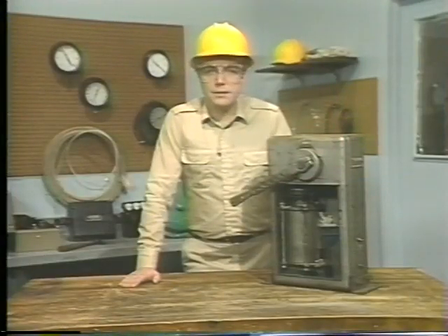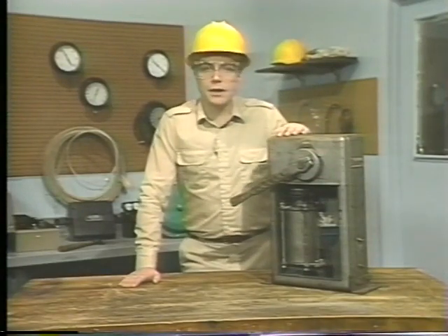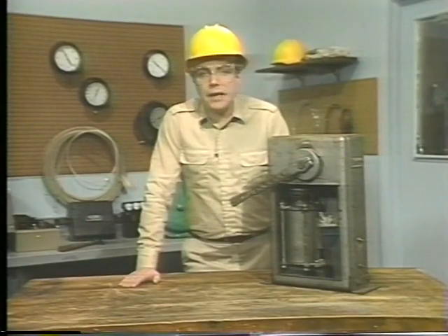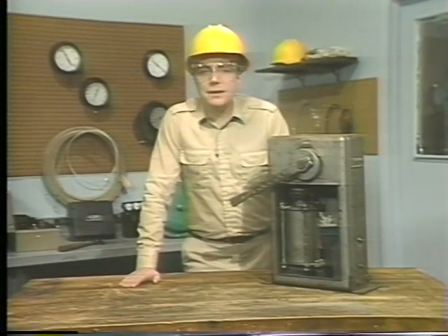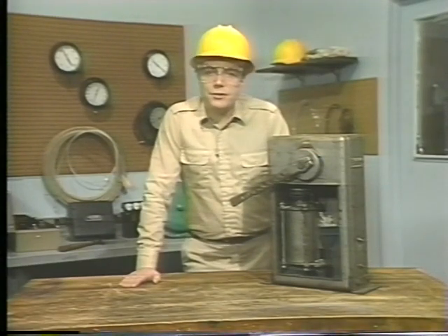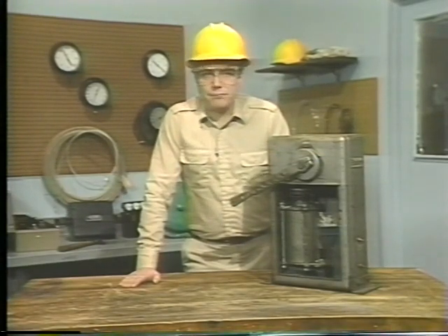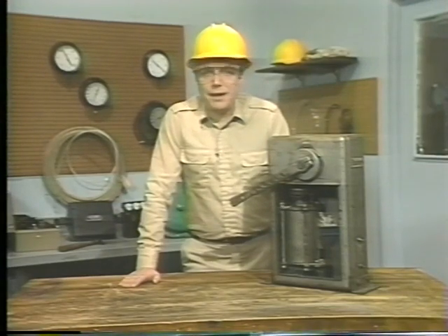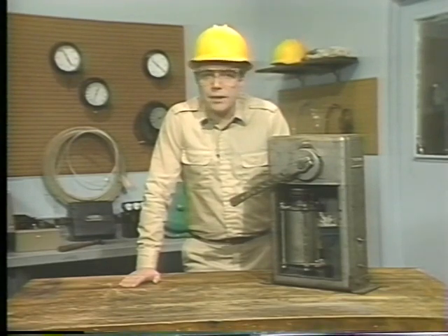Those are the main parts of a typical pneumatic piston actuator and some of the kinds of wear and damage to look for. Generally, piston actuators are dismantled and cleaned on a regular schedule. Your plant maintenance procedures will usually contain this information. Although most piston actuators are basically similar, it's always a good idea to refer to the instruction manual for any actuator before taking it apart.